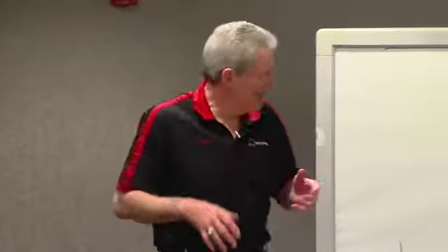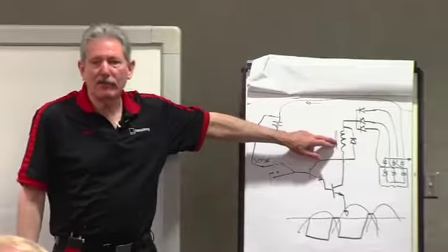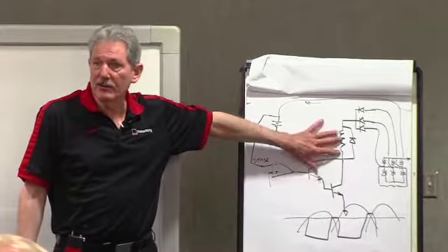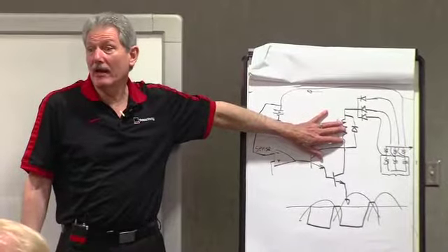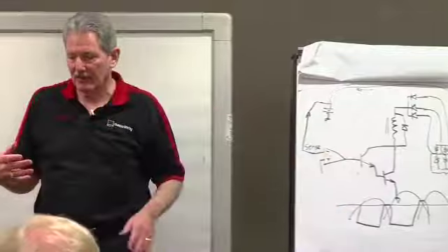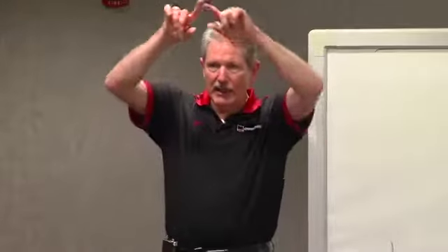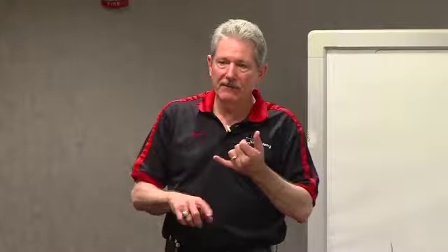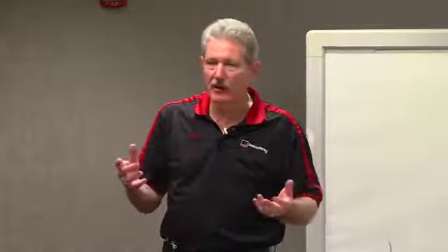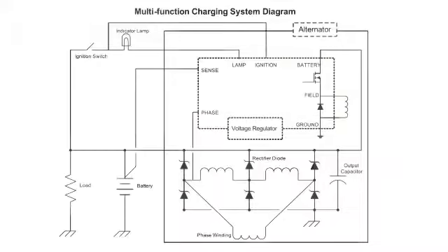We were also, back in the day, using 4 ohm fields. Well, with CS130, we needed to go to a 1.8 ohm field. And you can't use this technology, and I'll explain that in a minute. So we got together with REME, and they said, here's what we want. We want high efficiency, low cost, high performance, all these things, and we just started designing that and developed the first multifunction regulator, and that's in your pictures.